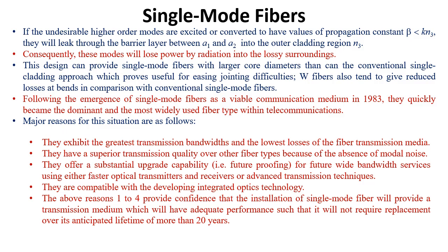That means once you lay the fiber, whatever the upgradations may be, that fiber will be compatible with all those upgradations for 20 years or more. So it is very, very flexible. Okay, so that is why people have shifted from multimode operation to single mode fiber over time.